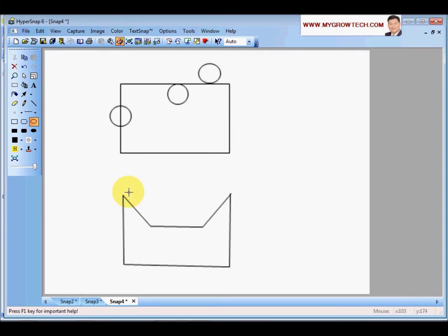How about touching? Touching means that you cut until the tool touches the boundary. Okay, the cutter touches the boundary. This is touch. Okay, that's why in 3D, the best option is to select touch.